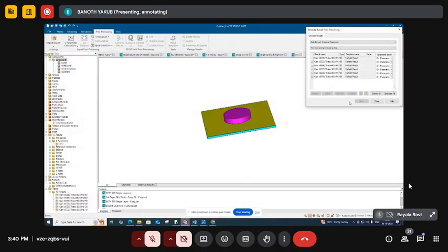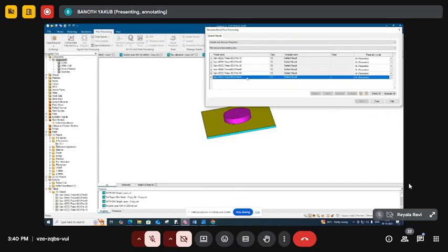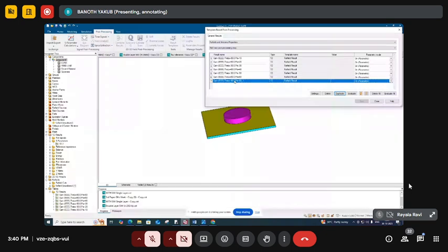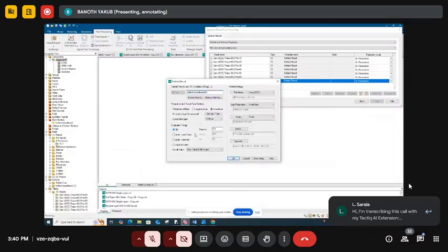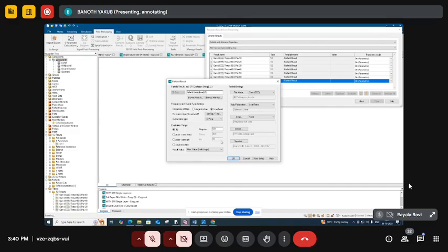Yes, sir. Okay. So now we can see how much gain our particular antenna design achieved. For gain purposes, we can select any gain angles. Go to duplicate, double click on that one. Here in the evaluation range, just change single direction to 3D. The step size is increased to 5. The theta angle will automatically change. The theta and phi angles you can change here.